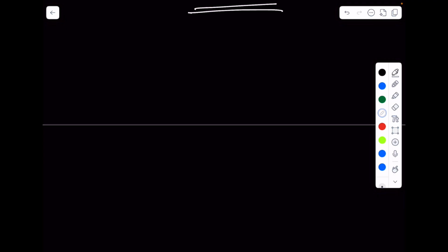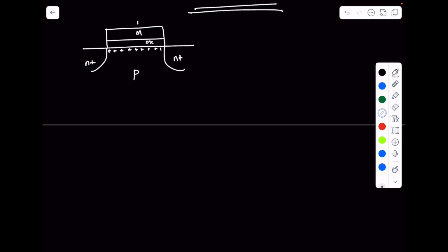So what we're trying to say is, let's assume that this is a certain semiconductor, right? This is your metal, this is your oxide, right? And there is a certain Vt that is set. It's an NMOS, so there's a certain Vt that is set in the device. Now the question is that you can modulate the Vt by applying a sheet charge at the surface, either by applying a positive charge or by applying a negative charge at the surface. And so we need to find what that needs to do. So first part is find the Vt of the unimplanted device, right?